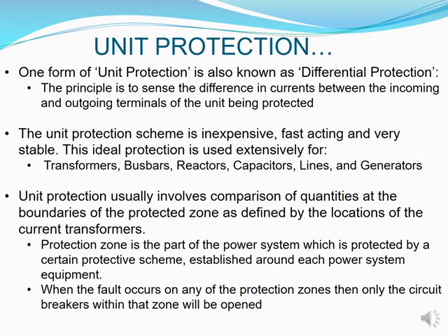Once we talk about a zone, it might be 1 or 2 units put together that are closely linked to one another, and we talk of them as a zone. So if you had a protection within that unit that did not trip out, then your zone can look at whatever has gone wrong within the system and take that entire zone out while the rest of your network remains in place.